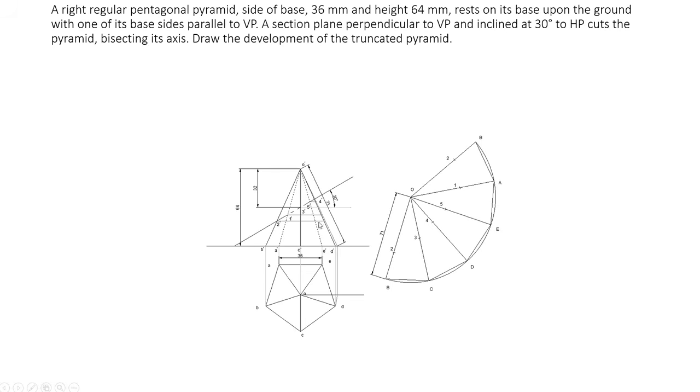You mark that distance from here to here and here to here, because B is coming two times. The first point and finishing point will be B. You project 2 dash to this line, this length is the true length corresponding to 2 dash. So measure this distance, and you mark that distance on the line OB and OB. This is 2.